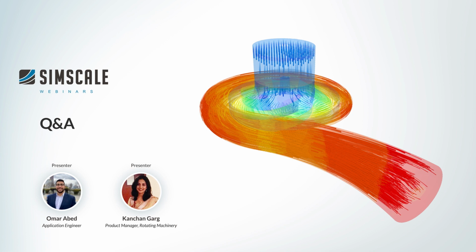The same way I've parameterized across several different flow rates, if I'm interested in looking at how suction head can affect the efficiency, I can look at one single duty point, one operating flow rate, and look at the various different suction heads that it operates under, to generate a curve at that one flow rate to be able to understand the best efficiency with respect to the suction head.